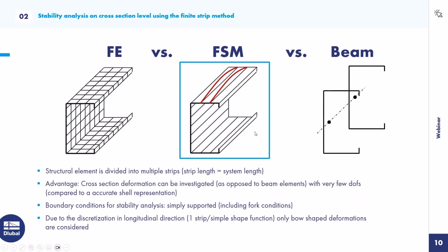And when we activate the finite strip method in the edit section dialog, a lot of these FSM members are generated, and the eigenvalue analysis is performed, and the eigen shape is stored, and also the critical bifurcation load is stored. And this happens on the go. So if we click it in the edit section dialog, it's done, and it finishes around 50 analyses in less than 1 second. So this is quite a nice advantage of this analysis method.